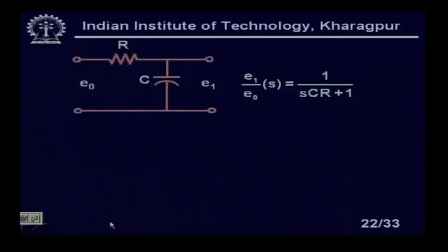Now again we are coming back to our simple RC circuits, which are used to make our dynamic measurements. In that case, the carrier frequency should be much higher. That means the excitation frequency should be at least 10 times higher than the maximum expected dynamic signal in the LVDT, right. What is the dynamic signal here? The dynamic signal is the movement of the core, which is the input. So the frequency of the dynamic input component should be 10 times lower than the frequency of the excitation of the LVDT.